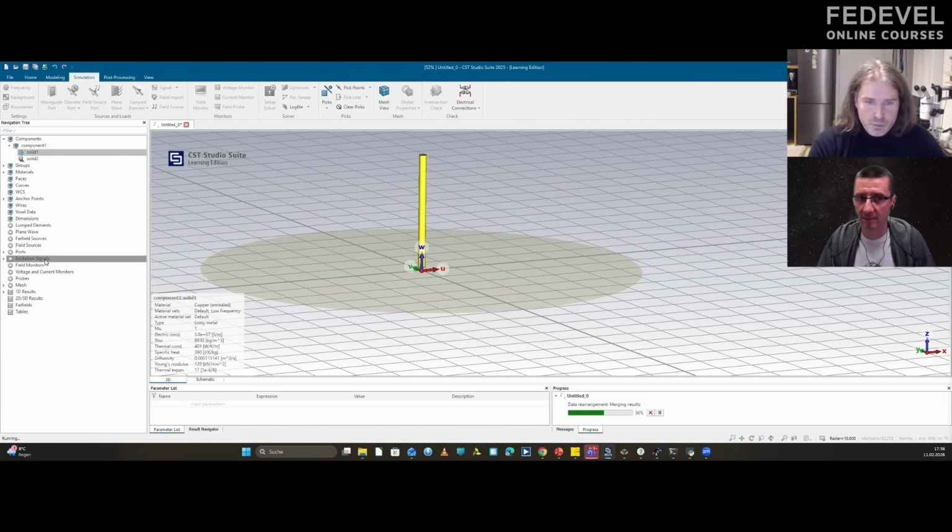But if you use the professional version, of course, you can import the model, and then you can implement your antenna, also the circuit if necessary. But I would recommend making the model as simple as possible, because otherwise the simulation time is increasing. And keep it simple, because in the end the simple models are also very close to reality.